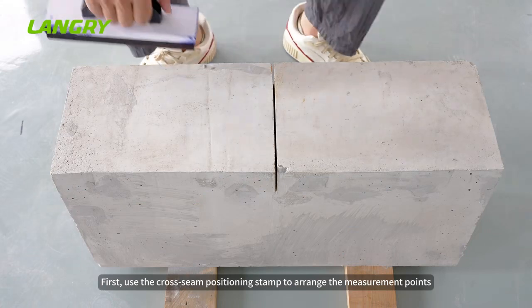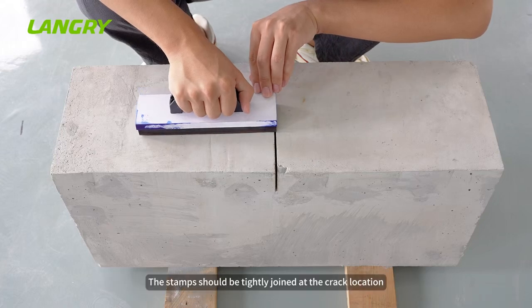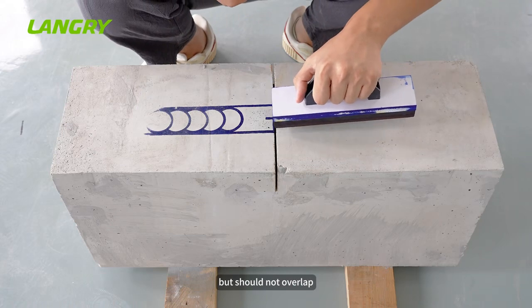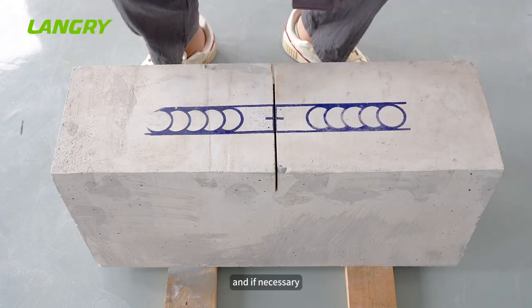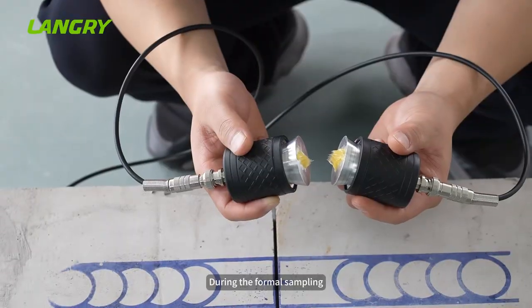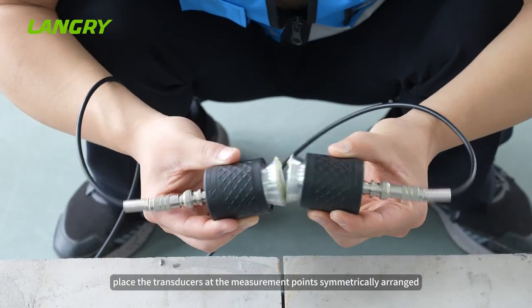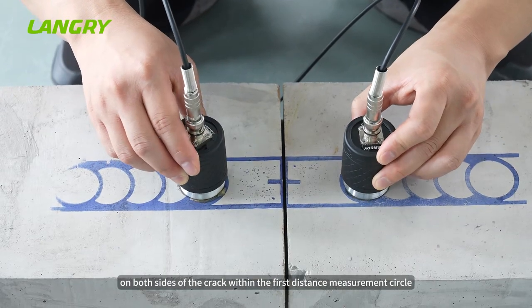First, use the cross-seam positioning stamp to arrange the measurement points. The stamps should be tightly joined at the crack location, but should not overlap. Avoid honeycomb and pockmarked surfaces, and if necessary, use a grindstone for polishing. During the formal sampling, place the transducers at the measurement points symmetrically arranged on both sides of the crack within the first distance measurement circle.